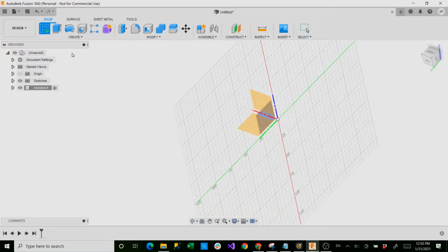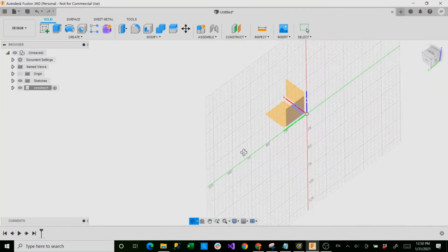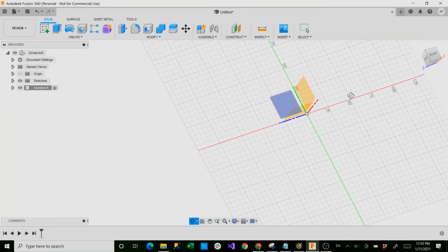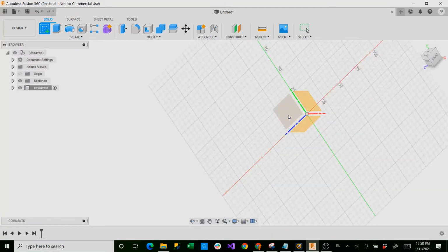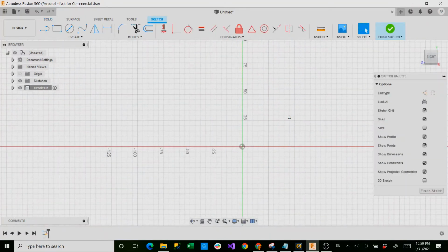You can create a sketch by clicking that icon there. And now we'll rotate around. And instead of selecting our usual XZ axis, we'll select our YZ axis. The reason for this is a revolve function usually revolves along a horizontal or vertical axis, which is our Y axis. And so for that reason, we chose the YZ axis.